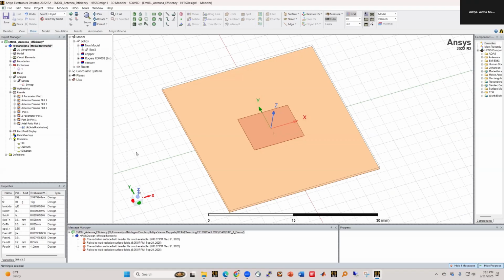Okay, hopefully that makes sense. So E theta would be our desired polarization, right? Because E theta in the E plane is, the electric field is oriented along E theta when you look along boresight. The boresight is along Z.